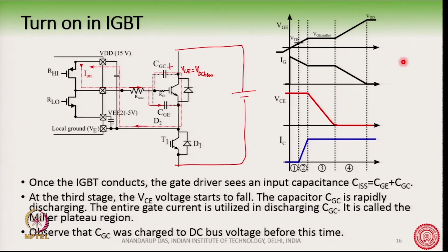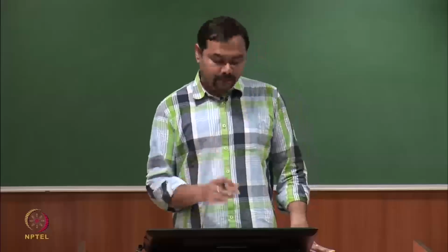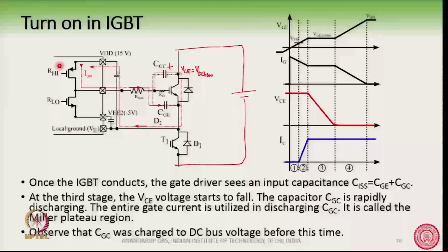In this region, this capacitor is discharging tremendously, and a huge amount of charge is needed from the gate driver to discharge this capacitor in the Miller-Plateau region.